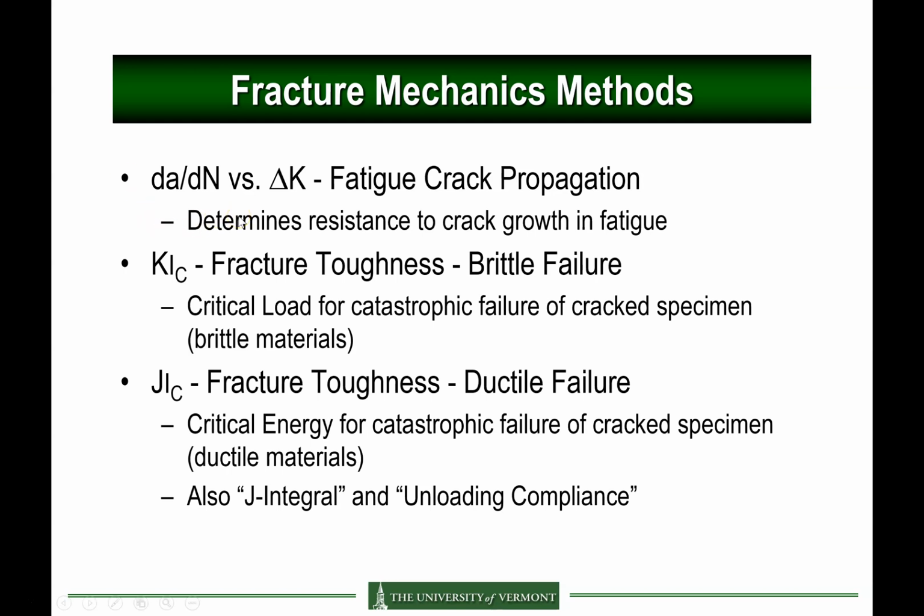We can use fracture mechanics to study fatigue crack propagation. In this case, we'll be measuring the change in the fatigue crack growth rate, da/dN, where N represents the number of cycles in fatigue, as a function of the stress intensity factor range, delta K. Okay, so that relates to fatigue.